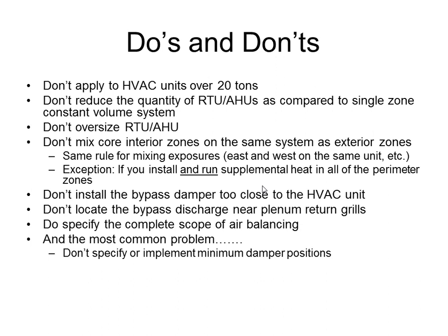You never want to reduce the quantity of air handlers or rooftops to do zoning. So if you size a building and you decide, hey, I need to do 3 rooftop units at 10 zones apiece, you do not want to take one of those rooftop units out, put in a 20-ton and do zoning. You want to use VVT systems when you already have this right-sized rooftop, and then you want better comfort, better control with zoning.